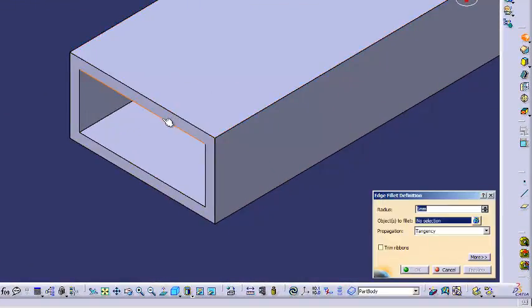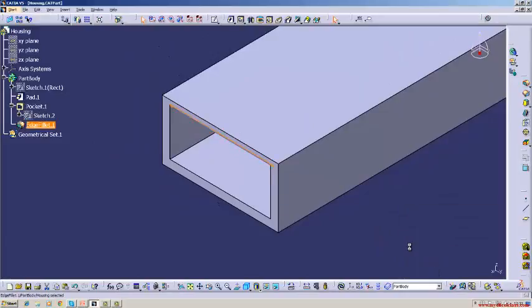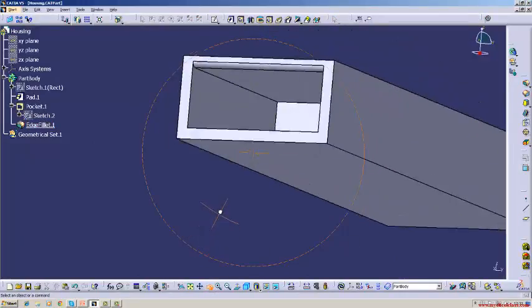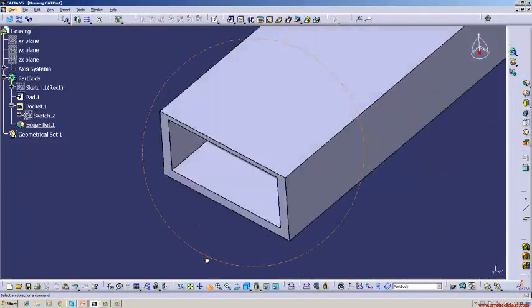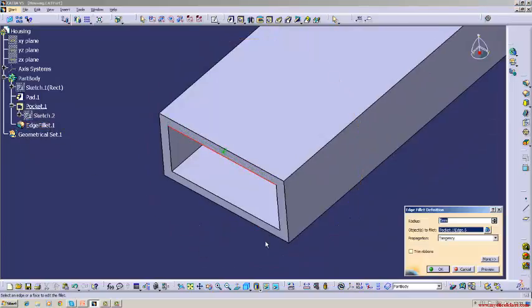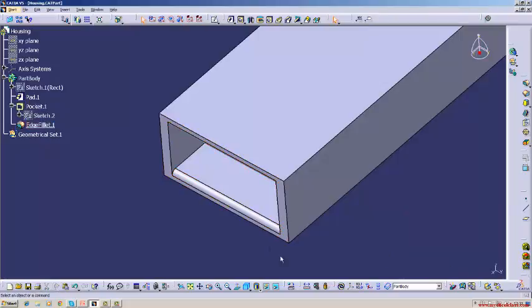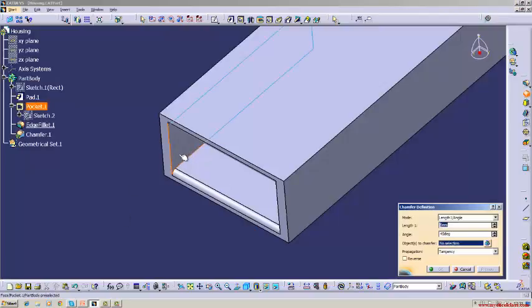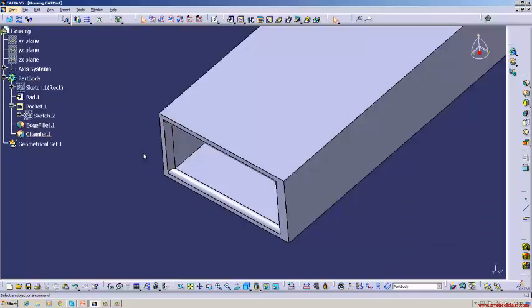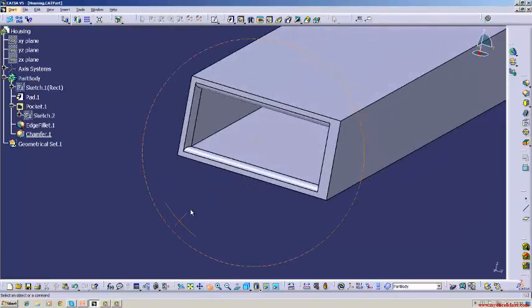You want to have, this is fillet, which is the radius. See, it is radius. It is a semicircular shape. See, it's been added. You want to add another one? Add. You want fillet in both sides and you want to add chamfer, you have to create separately. You add chamfer here. This is chamfer and that is fillet. See.